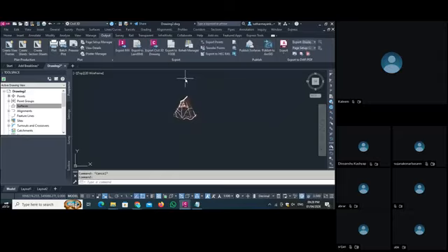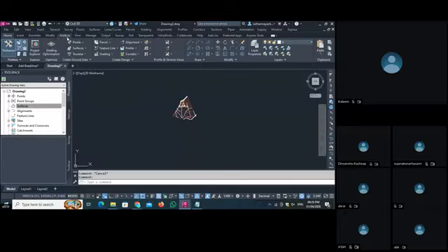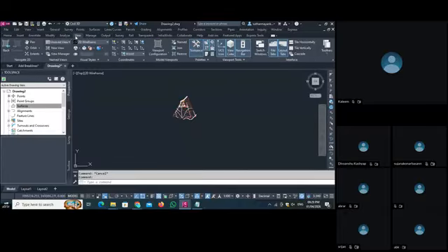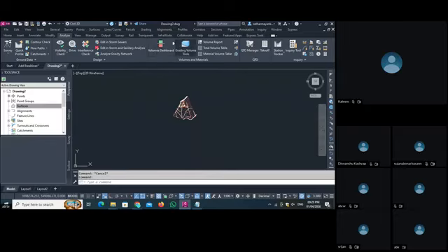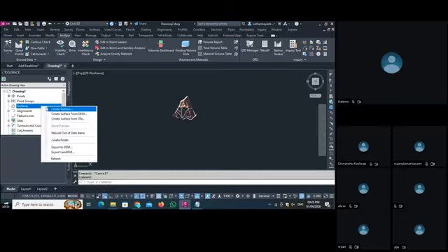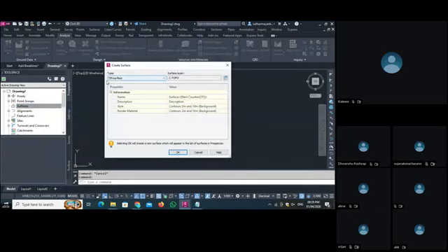And from where you can calculate your volume, you can see here. This is our volume dashboard. So when you create your surface, with the help of that, we can check the volume with the help of this tool. Okay, but now we are going with the surface only. So you have to select TIN surface here. In an interview, they will ask the types of surface, explain the types of surface. So you must know that there are 4 types, and mostly we are using the TIN surface.